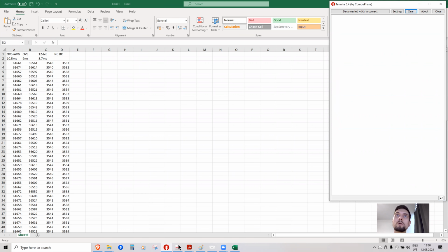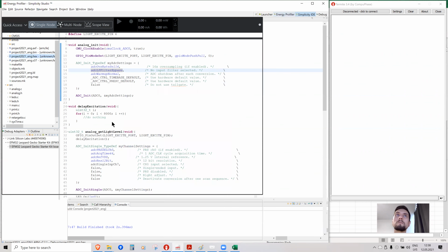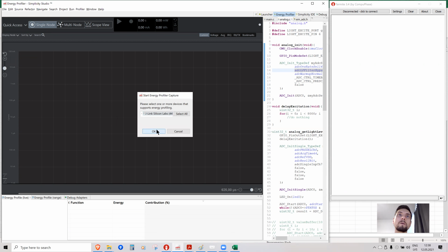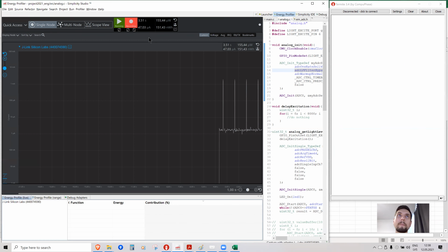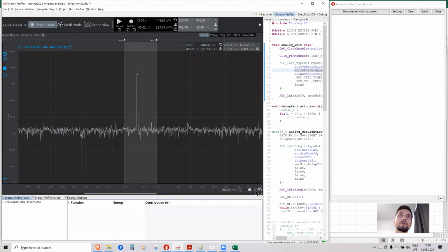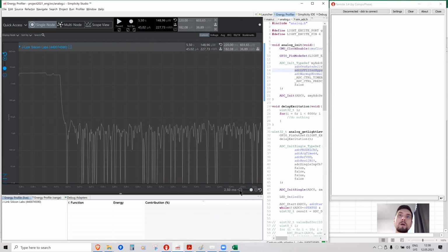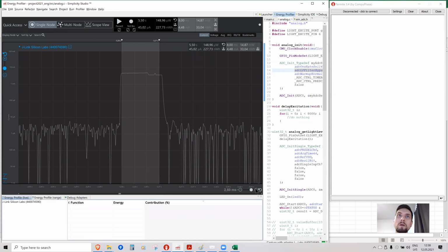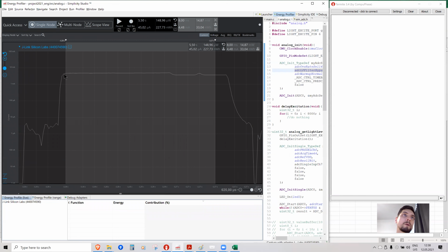The time should not change, but let's see. Actually, if we are not using the RC filter, we could have reduced the acquisition time, because this filter added quite a bit of time to acquisition.